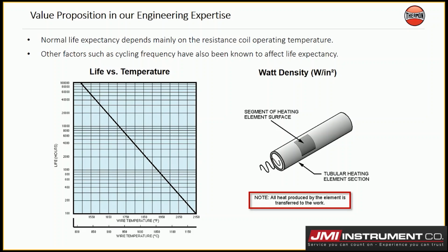If you have any impurities or heavy hydrocarbons, C6, C8 hydrocarbons, they can coke up on the element, which will have two effects. It reduces the heat transfer, which then results in an increased sheath temperature. So you have this snowball effect: as the element cokes up, or fouls, a term you'll hear from time to time, you'll accelerate the life or the death of the element. And ultimately, the sheath temperature leads to the coil temperature, so that's the resistance coil right at the center of that element. And higher coil temperature means lower sheath life.